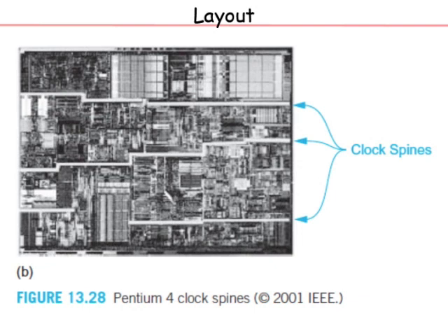Remember the RC delay due to the wires, and skews due to the RC delay, is basically almost eliminated. So then you have this large grid all across the chip, which gets excited with the same approach, you might have an H tree or something to excite it simultaneously from all points in the grid. Then you have the whole grid going up and down. So that gives you the lowest skew, but that is also the most power consuming approach.